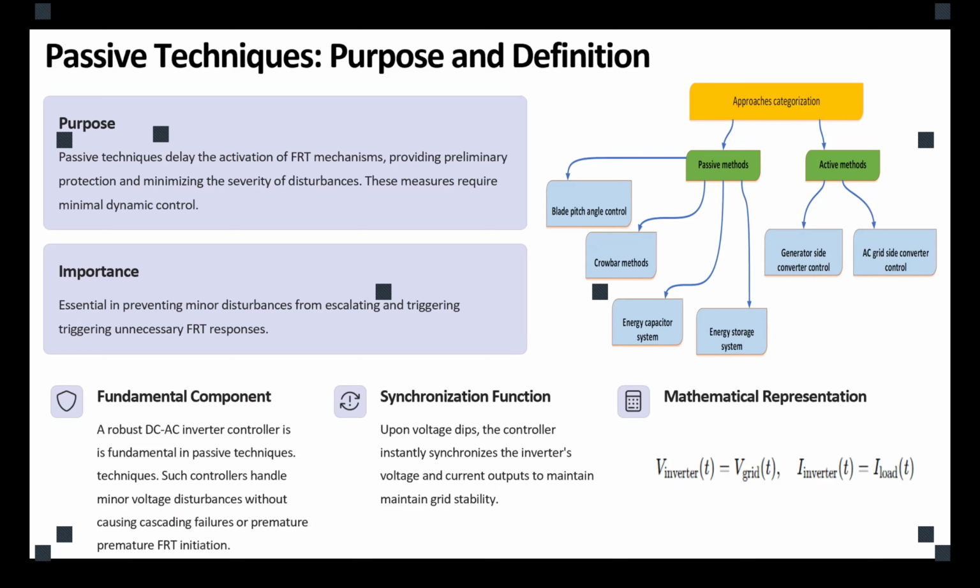So instead of instant reaction in our ideal protection scenario, we say to the protection system, you find the fault, wait for a few milliseconds or microseconds, or wait for 2 cycles, then react. If the fault is still there, then you can disconnect.